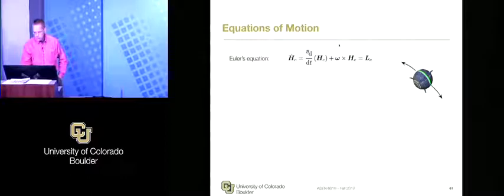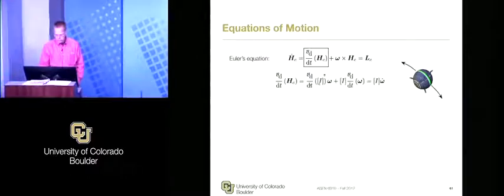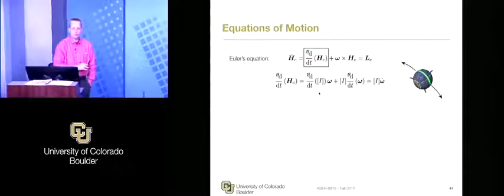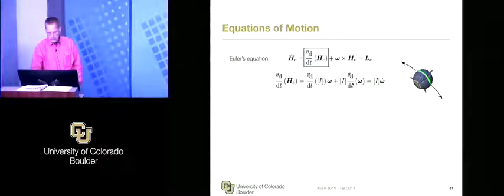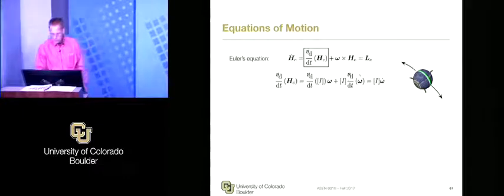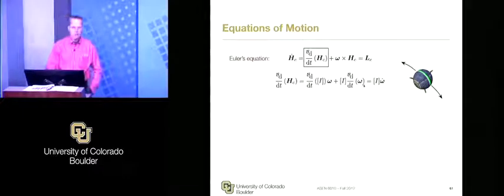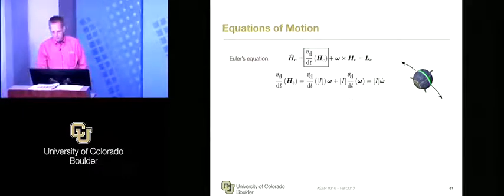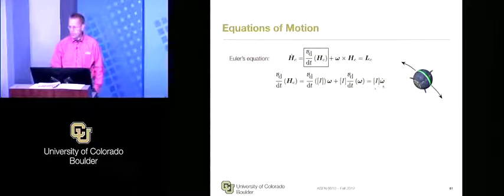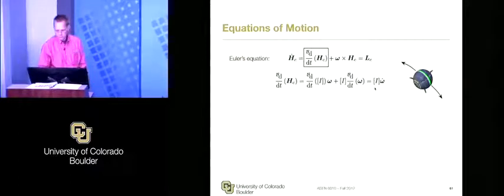Okay, so we're choosing to do this derivative because, explicitly writing it out, you'd have the chain rule, but this part is going to be 0 because it's a rigid body. So as seen by the body, the mass should never shift. And you just end up with this, and because of the property that Elena was talking about, the B frame derivative of omega B relative to N is the same thing as the N frame derivative. That's nothing but the inertia tensor times the angular acceleration vector, omega dot.